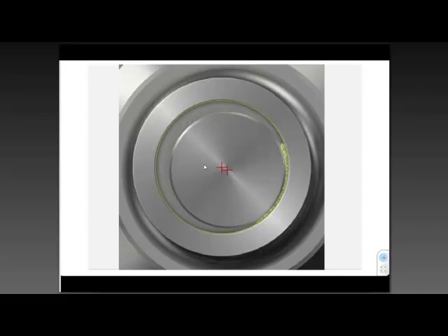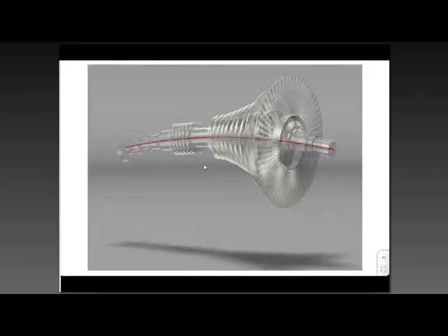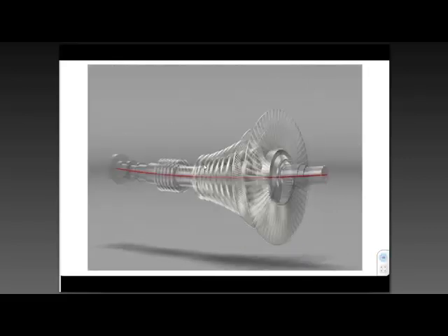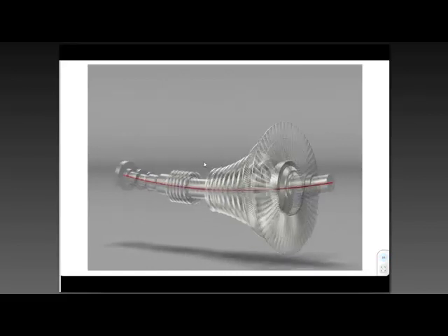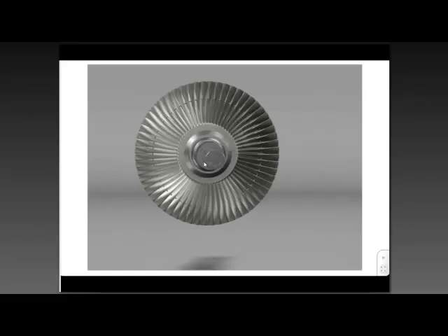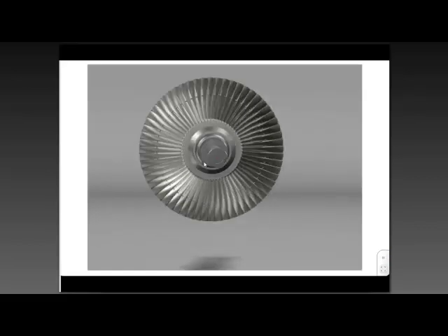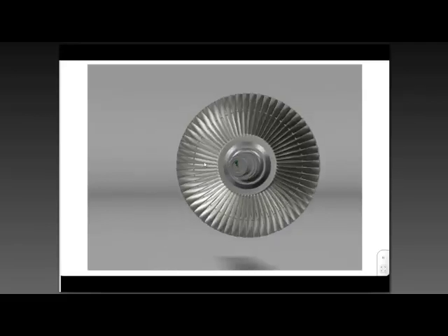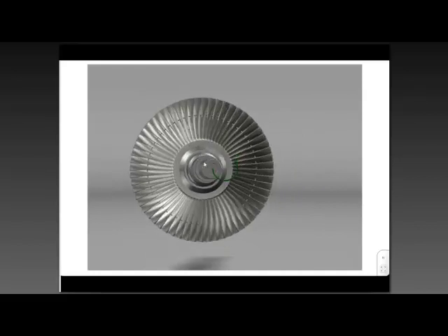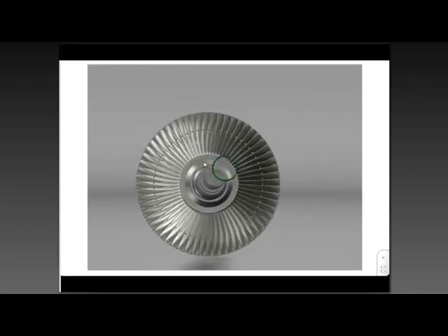We can also consider the entire rotor. You might think, wow, does it really flex that much? Well, like all my animations, I exaggerate, but this might be the first mode. The first balance mode is sometimes called first bending mode, but it's not technically correct. Not the time and place to talk about it. But anyway, you can see that it's moving in a certain way, and we would like to see how it's moving. And we'd like to see whether it's because of oil whirl or a bit of unbalance or preload or whatever it is. We're interested in what the shaft's doing, and putting two probes gives us that view.